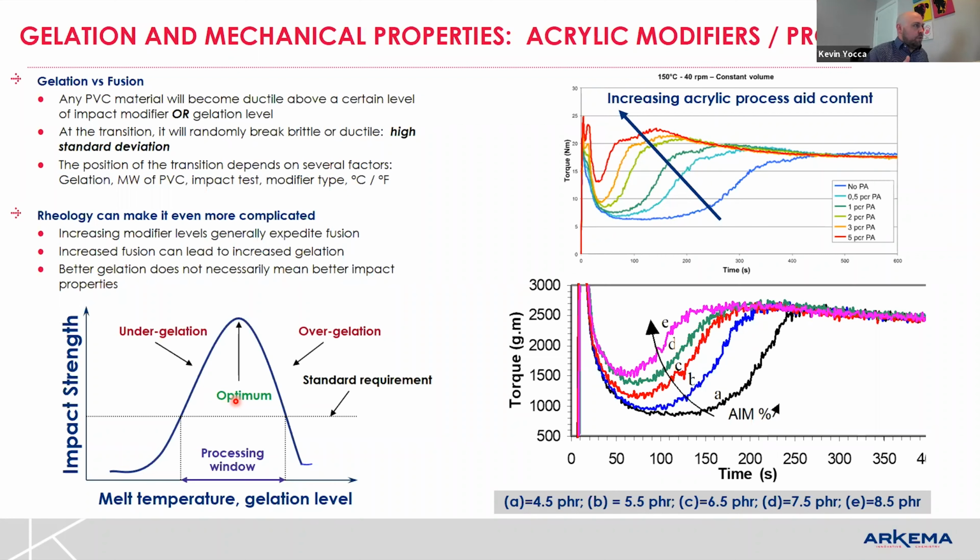So while we might, with more efficiency, meet our impact levels and have a very nice performing mechanical property, we might have more difficulty in terms of what the fusion time looks like. You might change the surface finish because there's less acrylic in the formulation. It might not be as glossy, right? All kinds of things can be affected just by changing something that you would think isn't really there for that purpose, but has a very big impact in the end on everything you're trying to accomplish with the balance of properties of the final article you're trying to achieve.